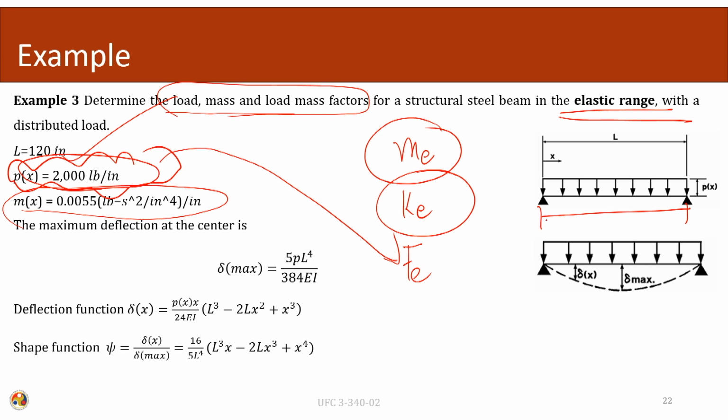We have been given a uniform, simply supported beam, and the behavior required is under some sort of uniformly distributed dynamic load. These things can be approximated by loading the beam uniformly with an equivalent static load.